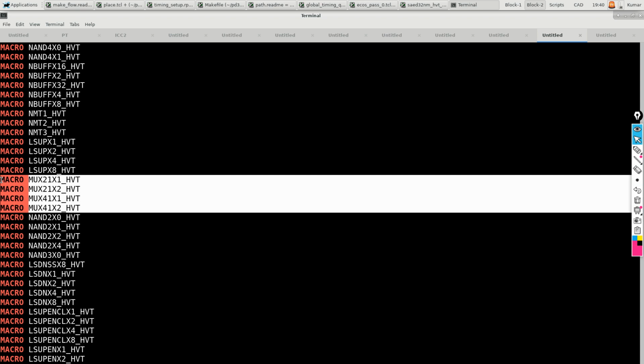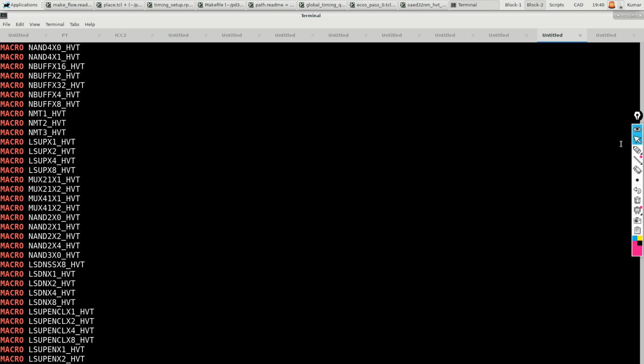Now, let me ask you a simple question. See, this is an AND gate, and then you are adding an inverter. What is the functionality? And this is a NAND gate. Now among these two, which one would you prefer when you are implementing a design? I prefer the NAND gate. Why? Because we need to place two cells rather than one. That will save area, and we can do the combination in a single cell. Okay, so you made the point: area.